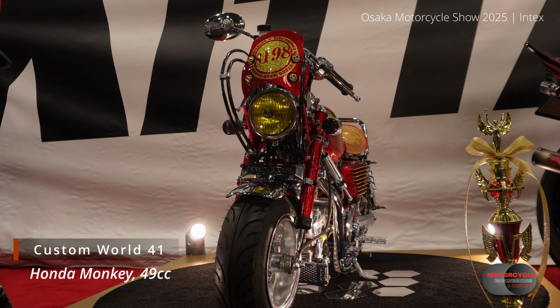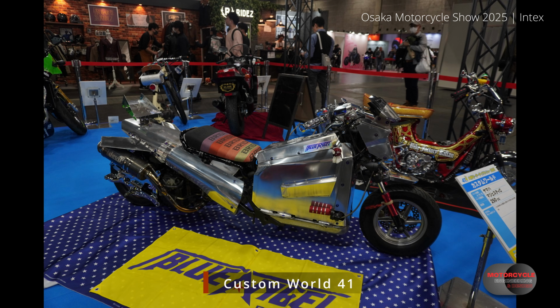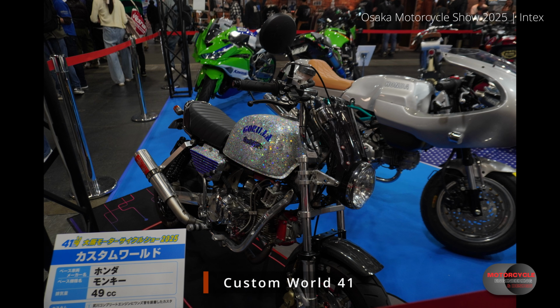On the flip side, however, if you have a larger diameter, we're not going to get a high enough velocity to encourage the effects that we want in the exhaust to aid in the scavenging. We'll also end up with a larger, heavier pipe. So what kind of effect do we actually want in our exhaust system?